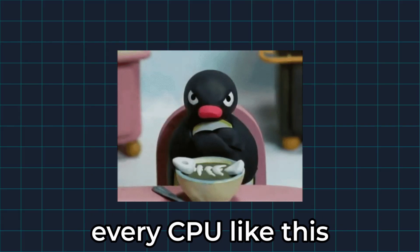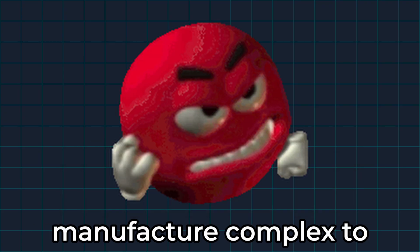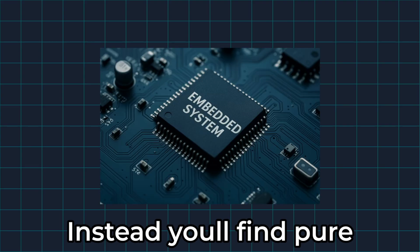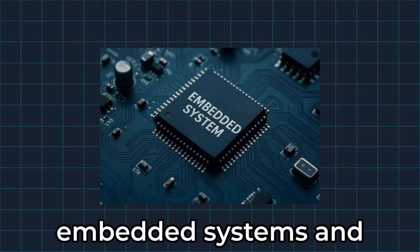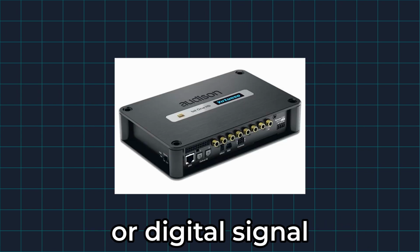So why don't we build every CPU like this? Well, Harvard is highly specialized. It's more expensive to manufacture, complex to wire, and can waste space if one memory block is full while the other has unused space. Instead, you'll find pure Harvard architecture in embedded systems and microcontrollers. Think your microwave, your car's engine control unit, or digital signal processors.